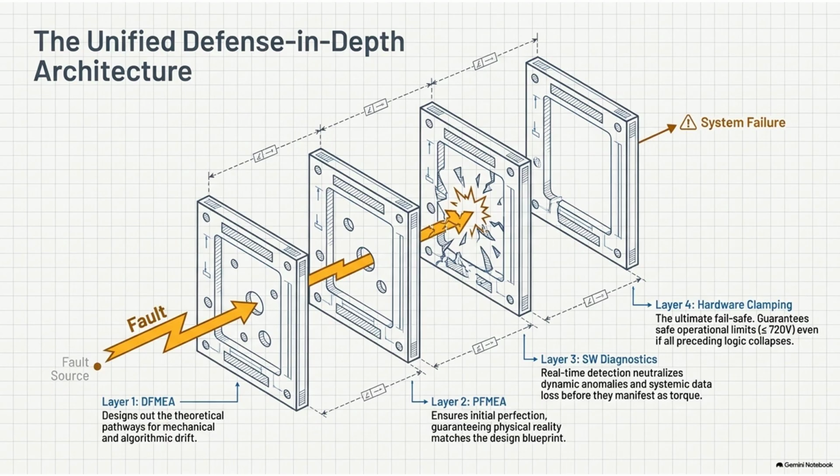Then the validation engineers use an FPGA HIL system. FPGA being Field Programmable Gate Array, high-speed custom hardware. Basically a high-speed, hardware-level hacker tool. They use it to instantly inject a fake 10-degree offset mutation directly into the resolver's data stream. So they lie to the computer while it's running at top speed, simulating that a screw just snapped and the resolver slipped 10 degrees instantly. Exactly. They inject the poison data, and they start the stopwatch.